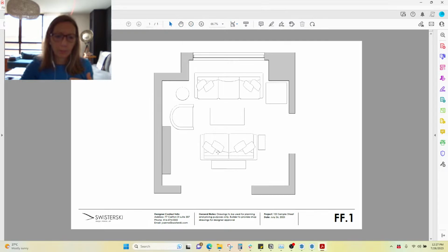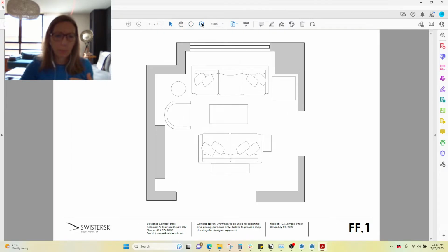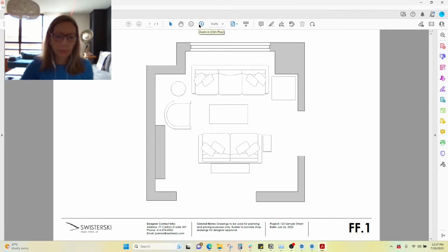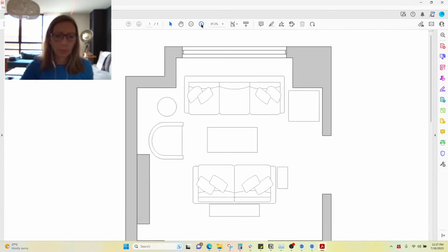SketchUp has, or that layout has, is that it has a hard time exporting curved shapes. Depending on what kind of zoom you have, you can see when I'm here it doesn't look great, but then I zoom in and it looks much better. So these curved shapes look way better when the JPEG compression is high. They're still not perfect, there's a little bit of pixelation there, but everything that's a straight line, even on low resolution, looks very good. So it's fine to keep it on a low resolution, high JPEG compression, because that just helps the curviness.